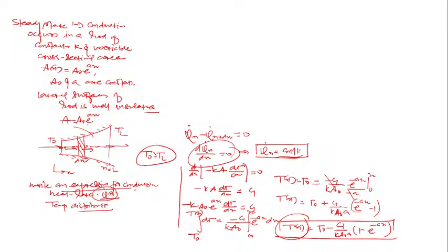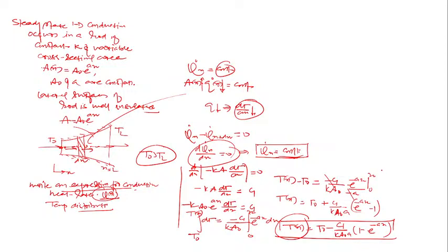My dear student, I told you in this case, since rate of heat transfer q dot x equal to constant, and q is area into flux at that x is equal to constant. Since area is going to increase, then flux will decrease in direction of x, and flux decreases. This implies dT upon dx decreases with respect to x from the Fourier's law.